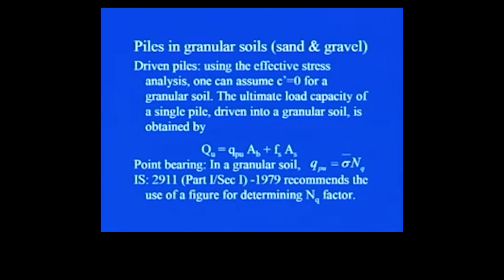Now, let us start with the piles in granular soils. Granular soils means that a pile is driven into sand and gravel. So, first, driven piles. Using the effective stress analysis, one can assume c prime, that is effective cohesion, to be equal to 0 for